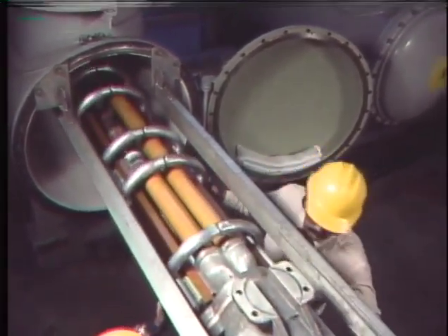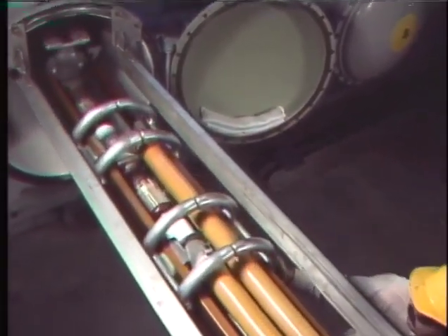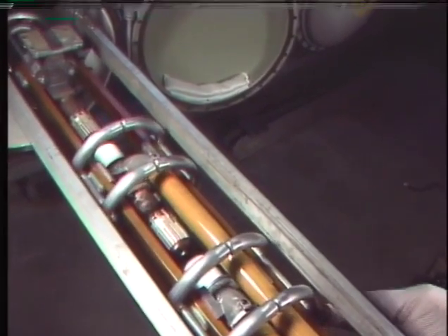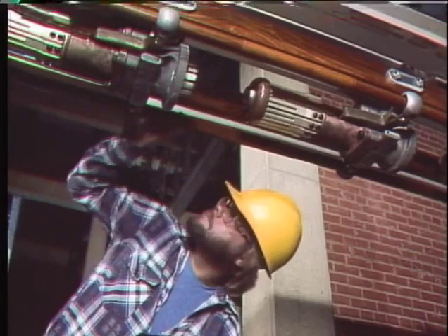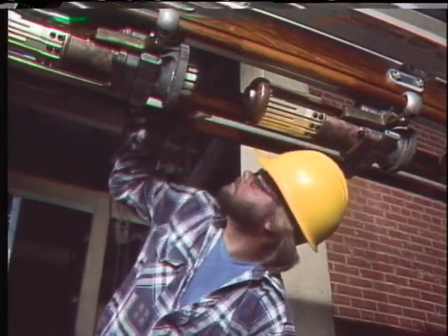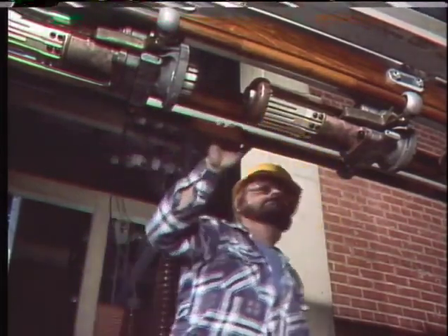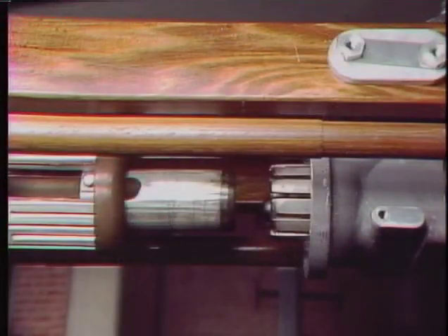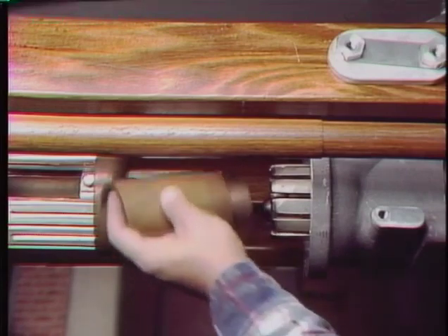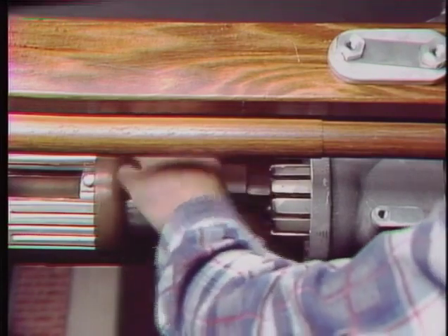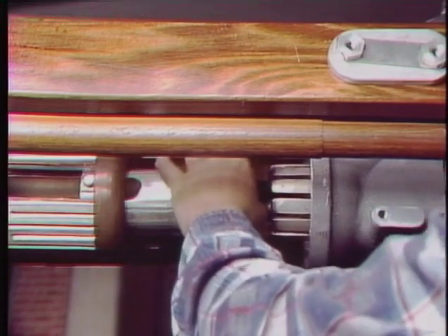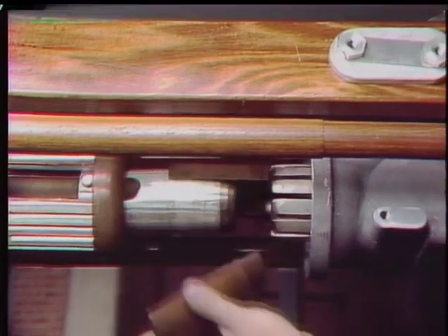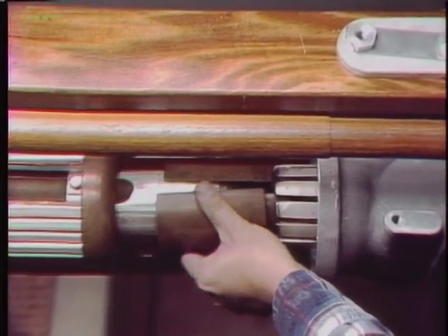These tasks may be more convenient with the mechanisms racked out of the tank, although it's not always necessary. The general inspection, servicing, and adjustment checks are similar to those done for most other breakers. However, contact alignment is checked a little differently. For this breaker, with the contacts partially closed, a special gauge is placed inside the stationary contact fingers and around the moving contact. If the gauge doesn't fit comfortably, if there is interference from any of the fingers, the alignment may need to be adjusted.